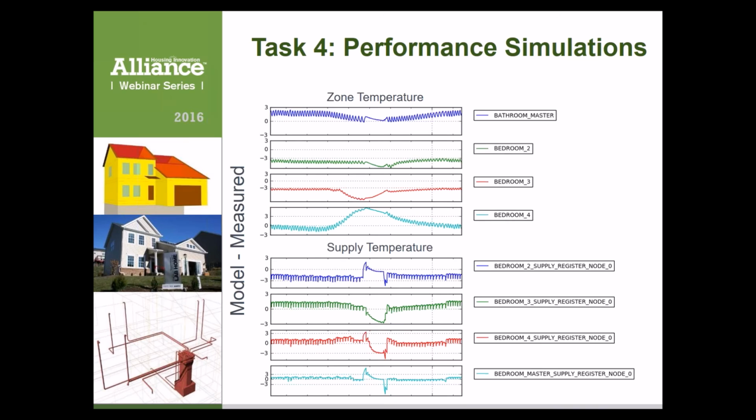Yeah, so actually some of the extreme peaks that you're seeing in the supply air temperature are just related to the way we were feeding the measured data into the model. What we were basically doing is taking the measurement at the supply plenum, right after the furnace coil, and feeding it into the model so that we were just looking at the temperature drop along the length of the duct runout. And there is that kind of period where you get some of these blips, and that was simply related to the way that measurement was taken and being fed in here. The period of interest is really a much smaller region relative to what we're looking at in the graph.